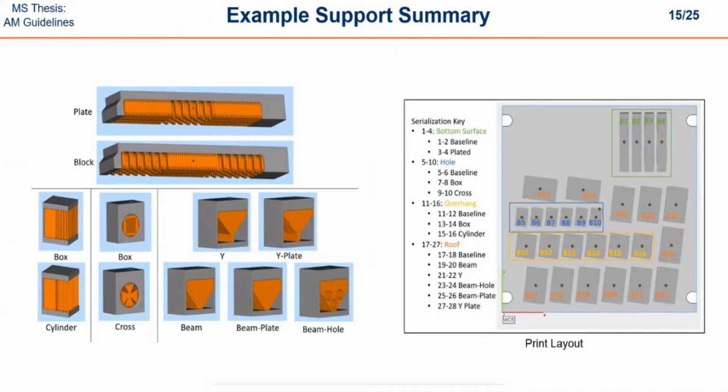And he shows us all the different kinds of support options, and you see here that for those different supports they have sort of serrated edges when they're attaching to the part, and this is to minimize the amount that's actually connected to the part and make it easier to remove.